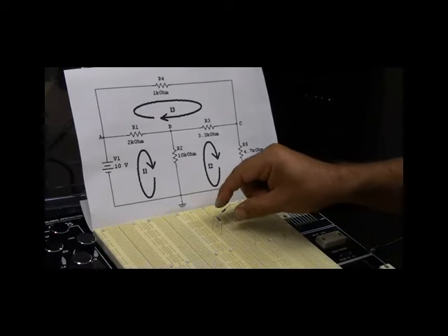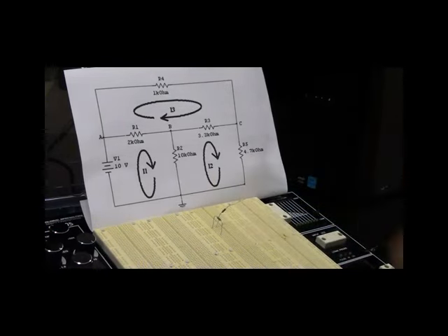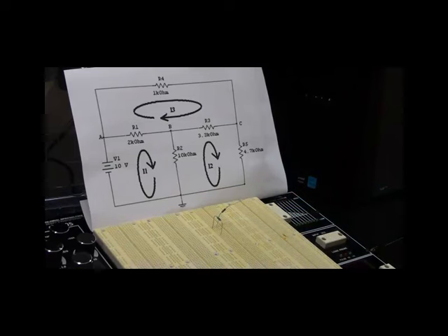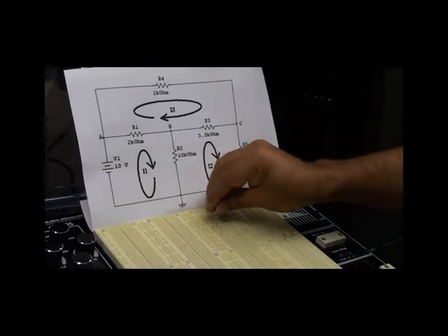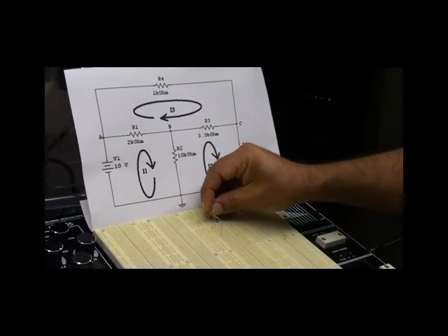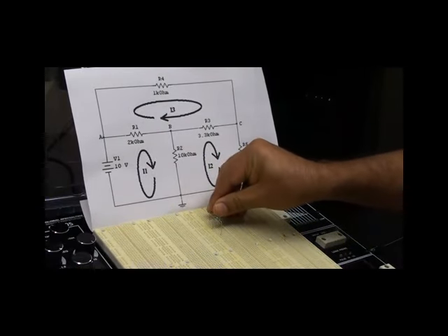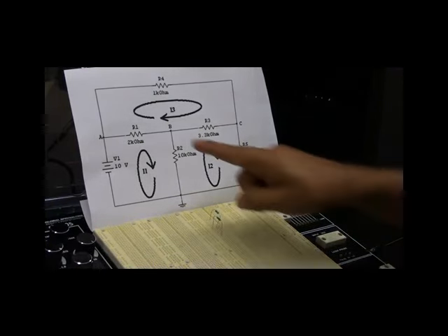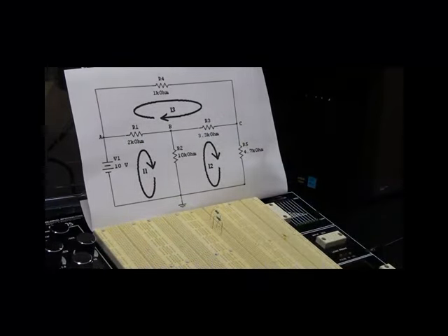This means that this pin is connected to this pin even though they are not touching, because they are in the same column with the connected holes. That's why they are connected. The other pin goes to another point, and again I make it horizontal. So you see I have two horizontal resistors right after each other.